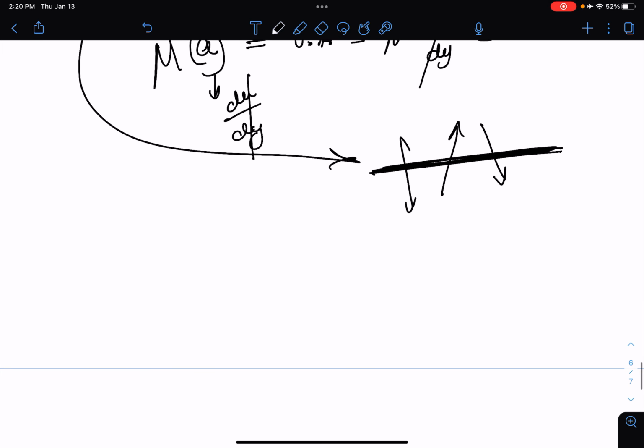The distance each molecule travels until it reaches another molecule is lambda. But the distance it travels until it reaches a plate, or a plane in general, is smaller than this, is 2/3 of lambda. So if you were to use that distance, make sure you are using the correct value, the 2/3 of lambda. I don't think anyone has arrived there yet.